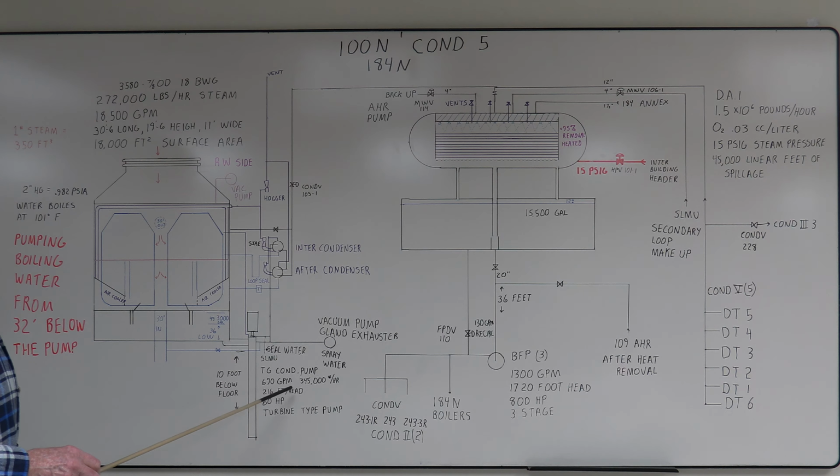The drawings show it was 10 foot below the floor, the bottom well. Some of these I've seen, they actually went down 33 feet or so. That way you might be almost zero here, then down at the bottom you're back to atmospheric pressure. So you've gained, the weight of the water brings the pressure back up, so it has a positive suction.